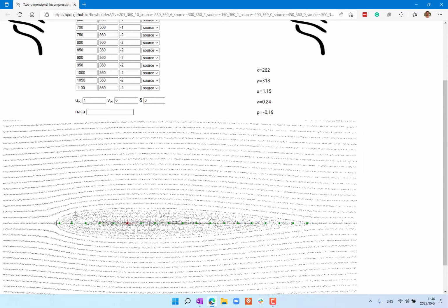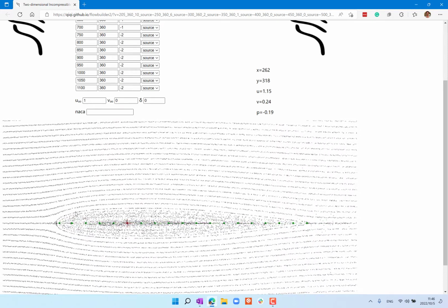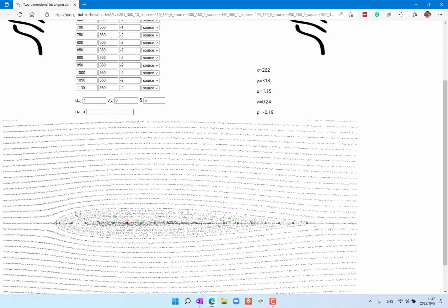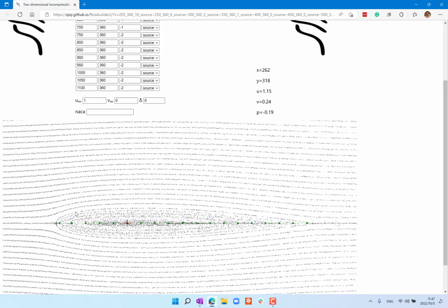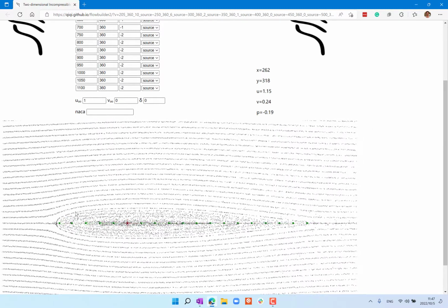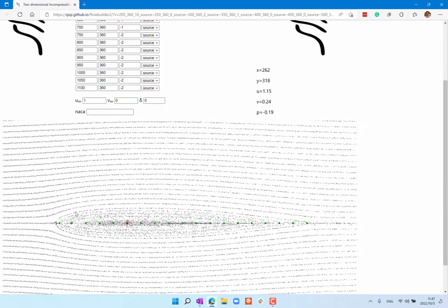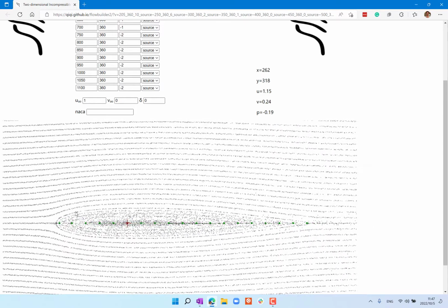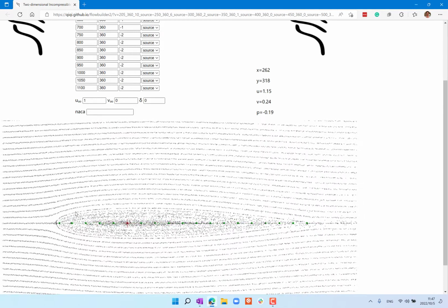And if you're designing airfoils, the way to reason about it, let me go back. When you're designing airfoils, you don't think about what shape you want. You think about what kind of pressure distribution you want. Because it's the pressure distribution that determines how much lift you get. By the way, the pressure distribution means how the pressure changes along the contour of the airfoil. It determines how much lift you get. It determines where the center of lift is, right?